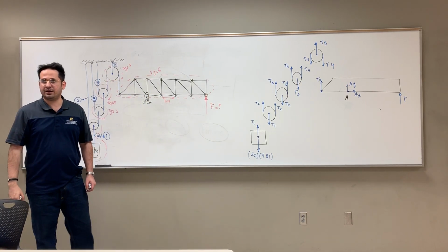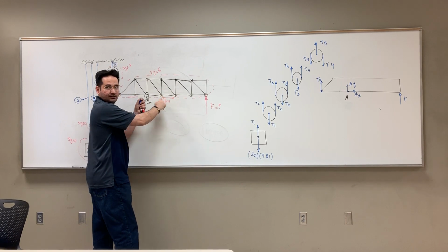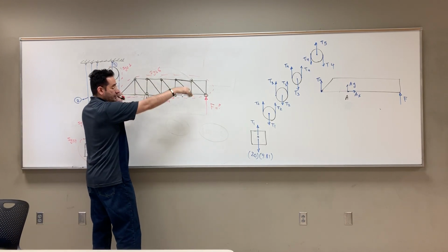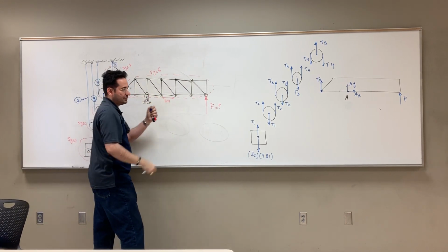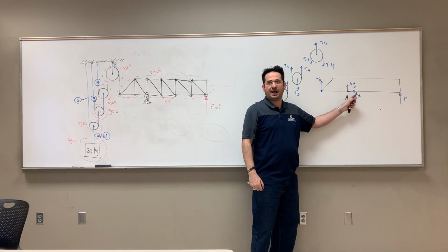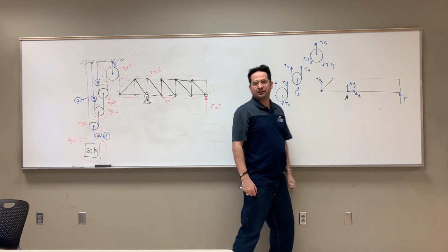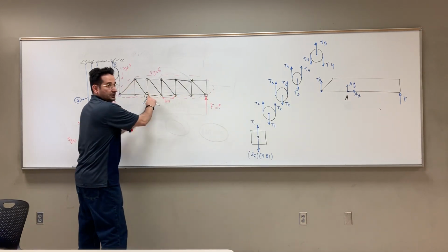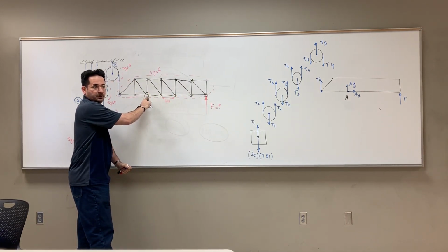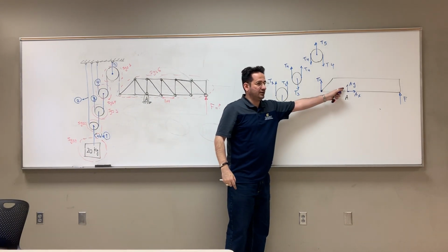Every time you draw a free body diagram, you say, can I move it in X? Like only this point, just forget about everything. Can I move it in X? No. So there is something resisting and you don't know it. It's a reaction. That's what we're trying to find. Now say, can I move it in Y? Can you move this guy in Y direction? No, it's pinned here, right? So there is a reaction, AY.